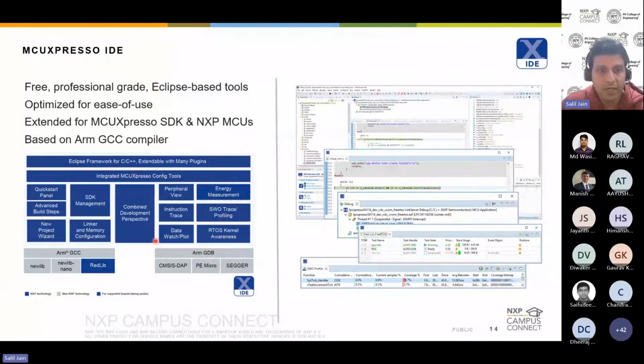On top of that, there is a development perspective. The IDE is the integrated development environment, which enables you to edit, debug, and compile your code. You are writing your code in C, but this IDE is compiling that code, creating the hex or binary file required by the controller, and also doing the debugging and checking the linking and configuration. Everything is managed by this IDE.